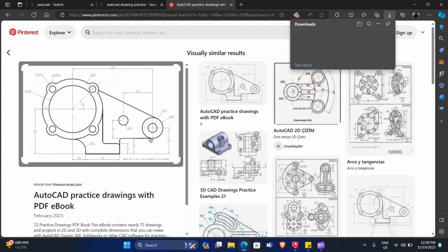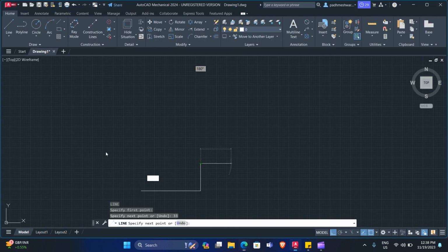Next we need to go this way, and this length is not given, as you can see, but what else is given is the center 170 from this point to this point. So basically all we know is this is 170 and this is 28. So what we can do is draw a line from this point for 28. Okay, and then we'll go here 170.